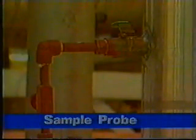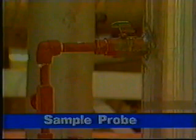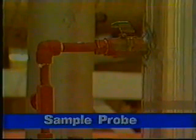Sample probes. Sample probes provide a location for collecting NGL samples while the meter tube is under pressure. A sample probe is inserted into the meter tube, usually downstream of the metering device because it can cause turbulence. The probe is never used as a vent valve.